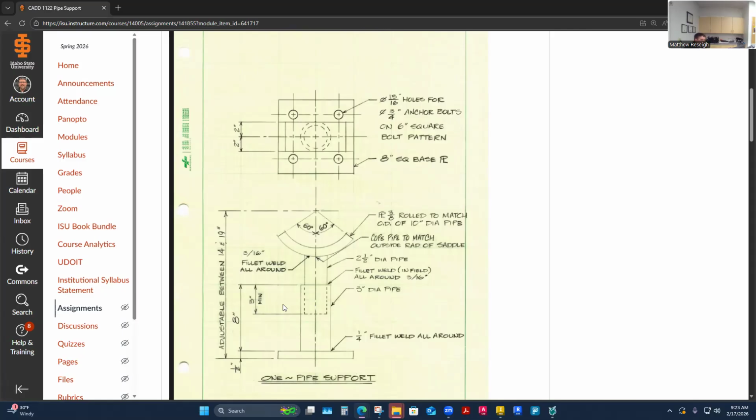It's probably for stability. Even if I weld around it, you just have those pipes fitting together. The more they telescope into each other, maybe the more stable they are. If it's 6 inches in there, you get a part that really can't tip easily. But anyway, it's something to watch. They want me to not be any less than 3 inches when this thing hits the 19-inch overall height that it can hit. So this thing has to hit 19 inches and maintain 3 inches of overlap. What controls that whole relationship is the length of this part that I'm making.